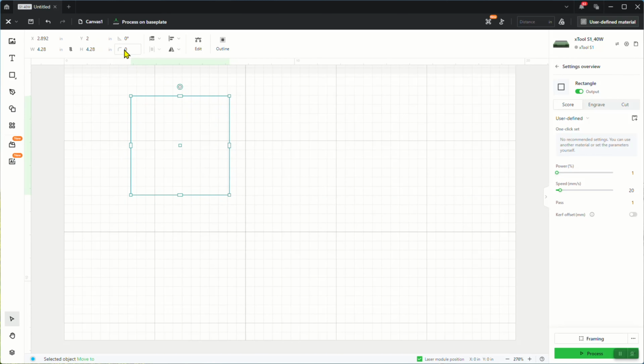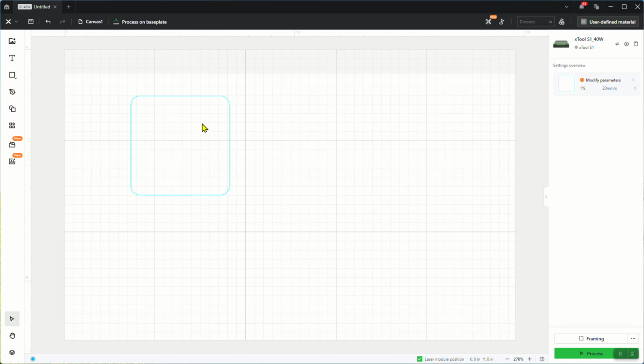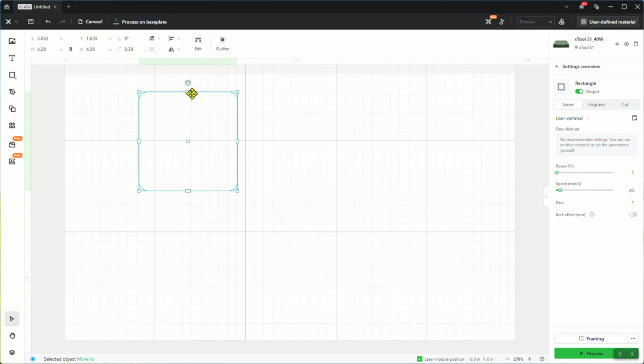Now, we're going to put a curvature on here, and the way that I figured this curvature out is, you remember the curve that I just showed you in the F1, is I took a 3/4 inch dowel rod and tried to fit it in there, and it was a little too small. So half a 3/4 inch, that's the diameter, so half of that is 3/8 of an inch, or 0.375, and I just went up 0.015. So that gives me a 0.39 here, and then I can get the curve on it. And that was a guess, totally 100% of a guess, but it worked out for me.